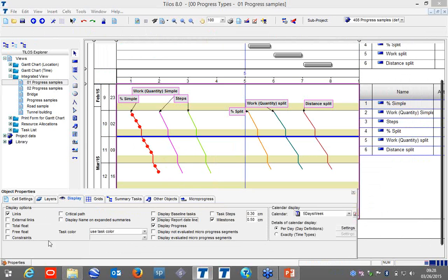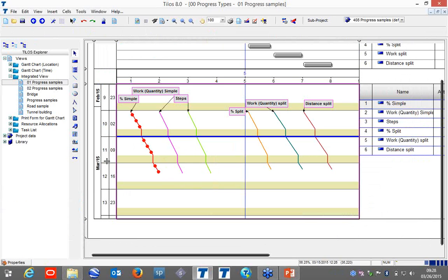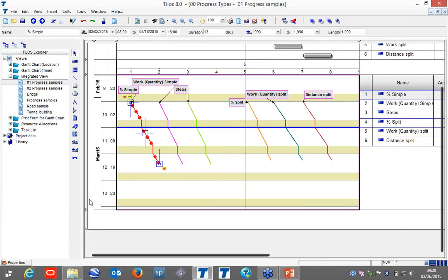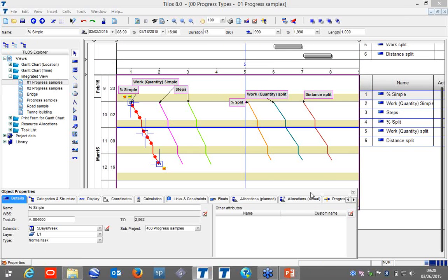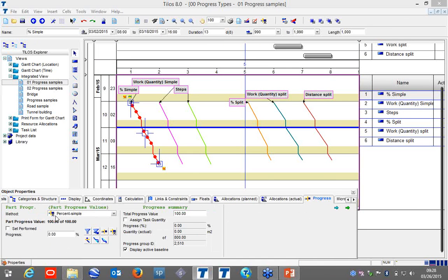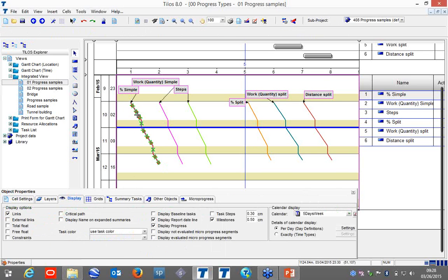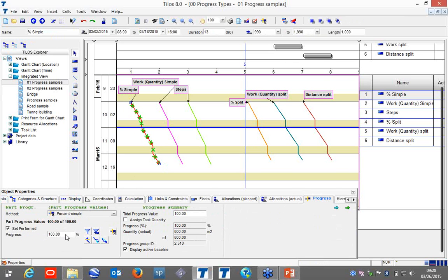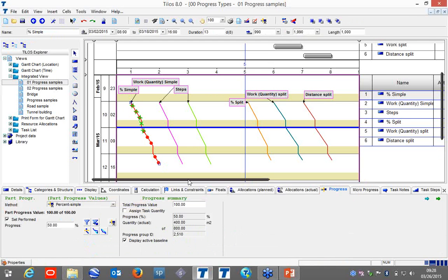And now I have the idea of showing different types of work, and now it is showing person simple. How we define it is the type of work, person simple. This is used to put only the progress, like how much, say 100%, we have completed. It just records completion. It doesn't consider the works, let's say now 50% is completed.